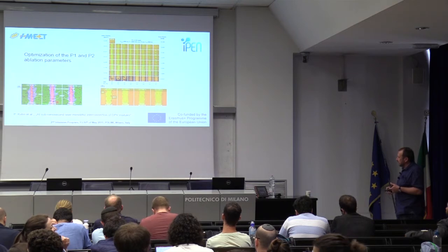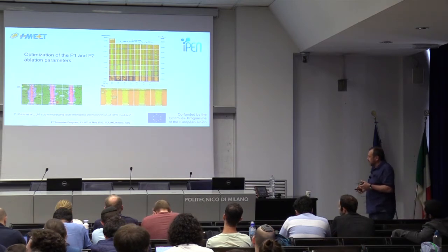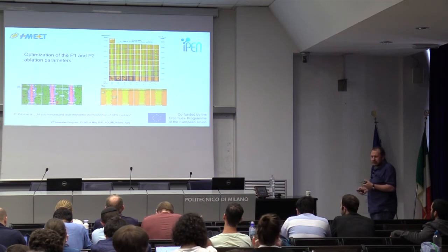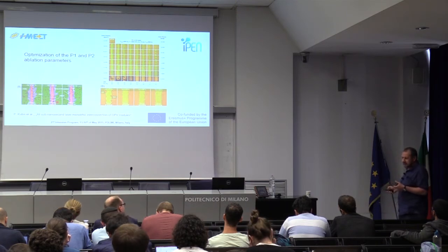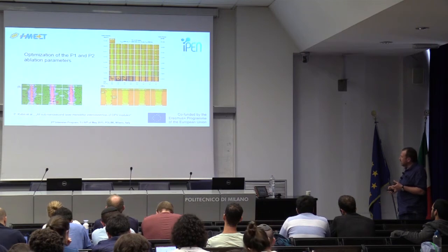And then doing the same for the P2, which is more complicated because if you do it with infrared light, then infrared light is not so strongly absorbed by the active layer. It penetrates the active layer and also damages the transparent electrode. And this is the problem.